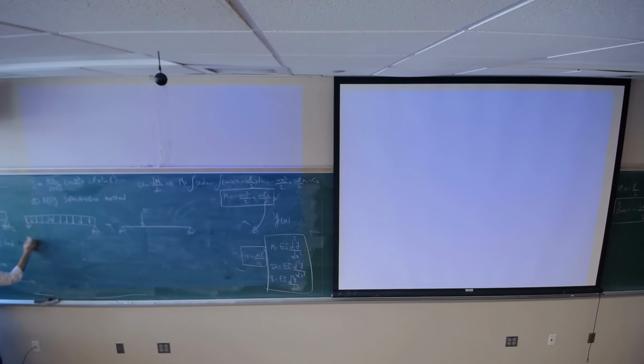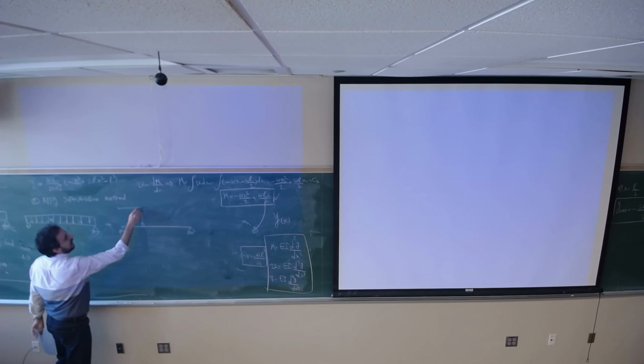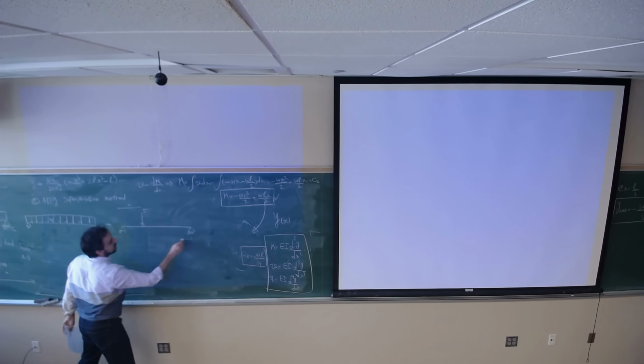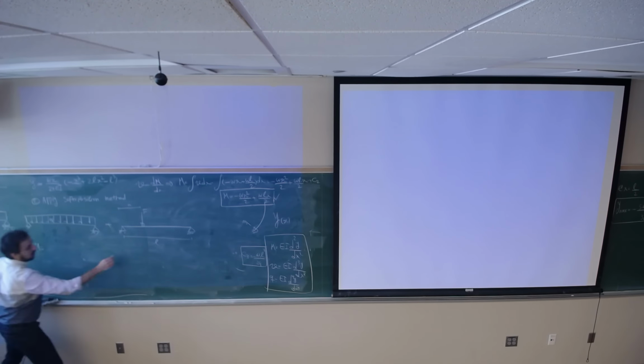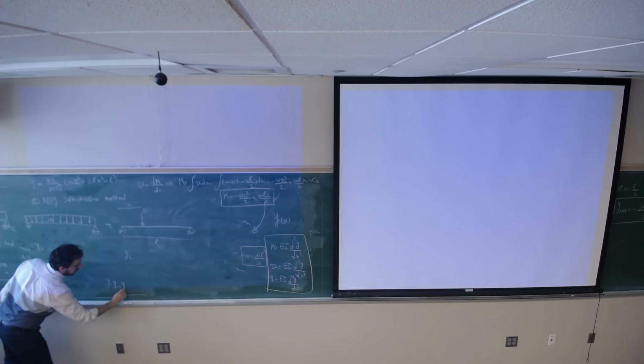Table A9 has the equation for this type of beam, with the length of L and distributed load of W, and also a cantilever beam with the length of L, where force F is applied at the distance of A. What would be the deflection? So you will find Y1 from here, Y2 from there, and add them up by applying the superposition.